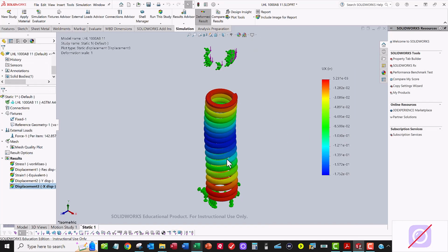So side to side, it's staying straight in the middle, but in the middle of the spring here, it's moved over. It's 0.17 inches. That's almost 3/16 of an inch. So that's somewhat worrying. My standoffs that guide it are only guided for the first half inch or so. So here the standoffs themselves are an inch tall. So this might be an issue I'm going to address later. I believe your springs are much shorter than this one, so I don't believe you've got buckling problems. But mine potentially has a buckling problem. So let's go look at the shear stress.